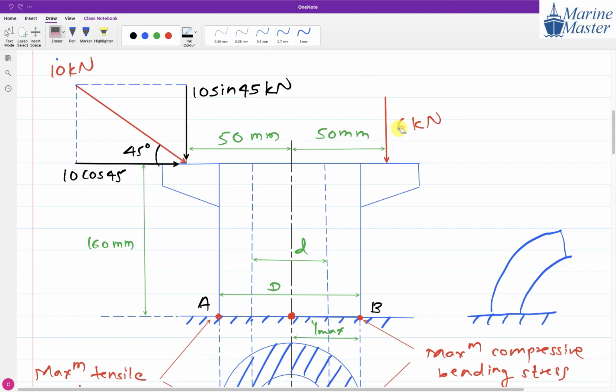So we consider this in calculation of F also, in calculation of M also. For the 10 sin 45, compression and bending, so F calculation also, M calculation also. But this 10 cos 45 is only for bending. No compression is created, so we are considering it only in the calculation of M.